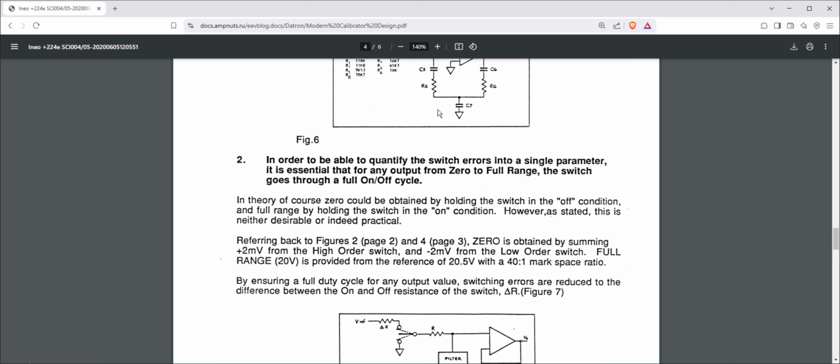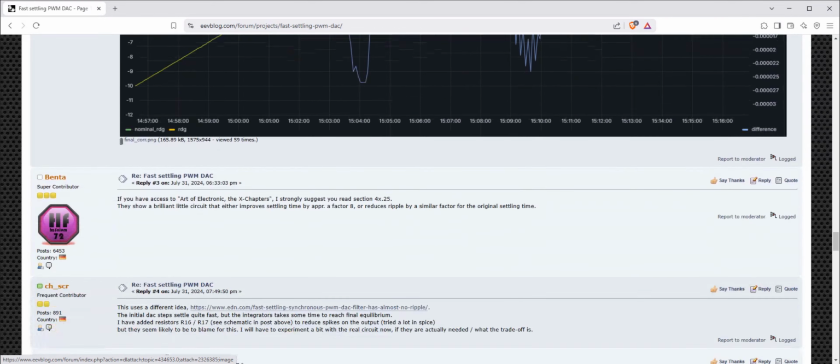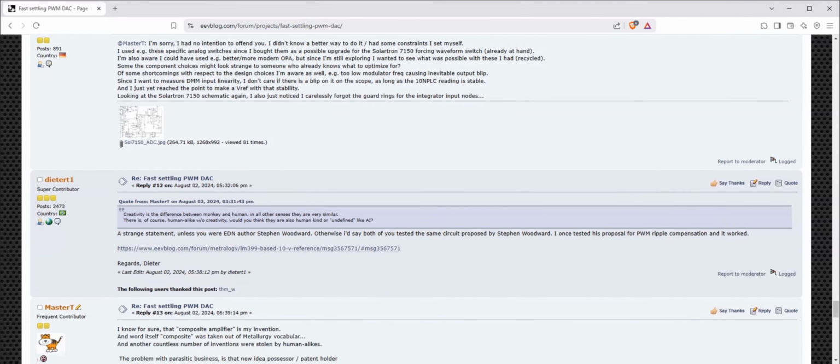It turns out that the Woodward circuit has been replicated quite recently, but the INL still ended up being quadratic, even after correction, never really reaching the sub-ppm linearity I was seeing. It looks like the secret of the compensation amplifier is not yet widespread.